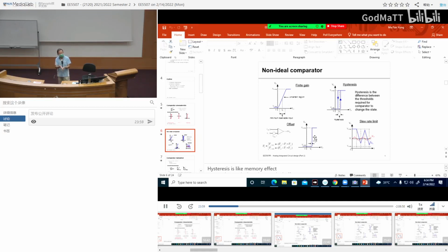You need to charge, right? You need a current to charge the output. As soon as the output is tied to some place where there's a capacitor, for the output to go from low to high, you need current to charge it. I equals C dV/dt. So you need current to charge it, and if you want a very sharp transition, you need a very big current.